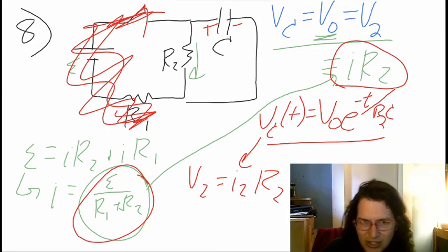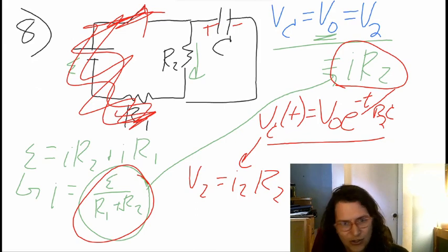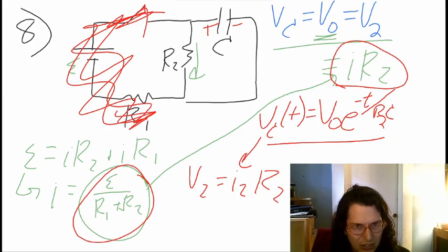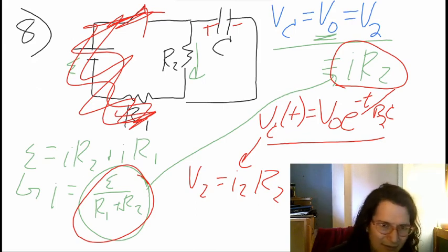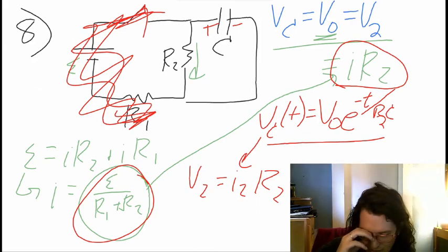Okay. So this one is a little bit of a complex sort of example of an RC circuit. And we are strictly discharging here. The charging process is a little strange because we have the capacitor and R2 in parallel initially. But ultimately, remember, we want to discharge down to 0. The time that's given is going to be the time to half of the maximum voltage, though it won't be quite the time to half the max.